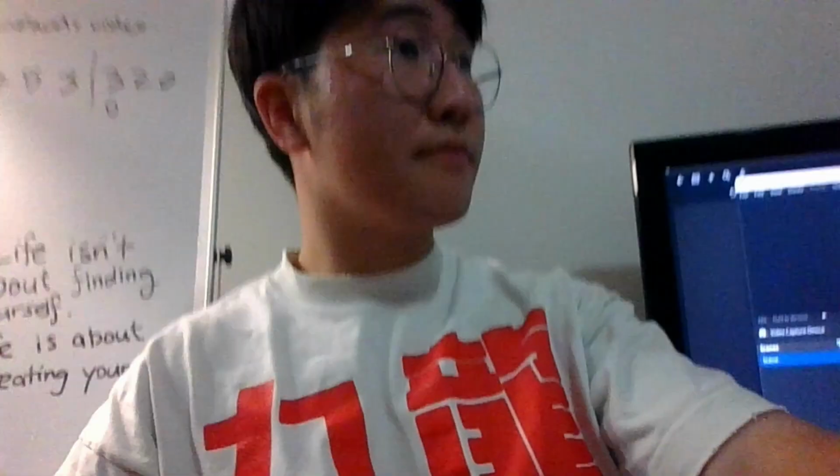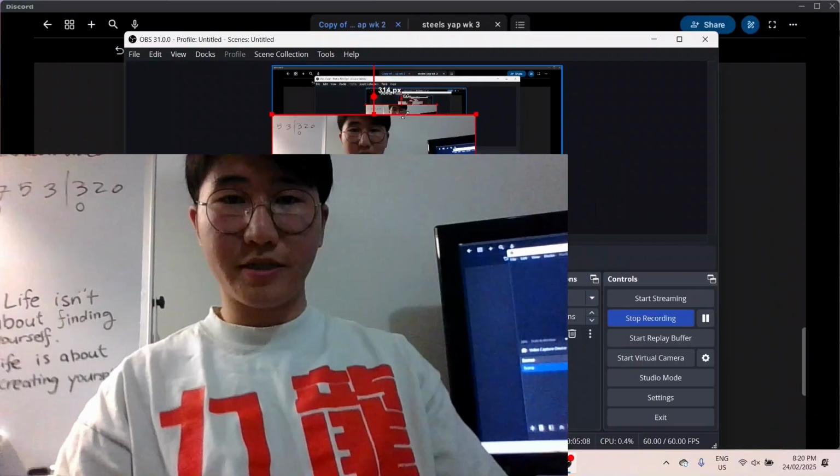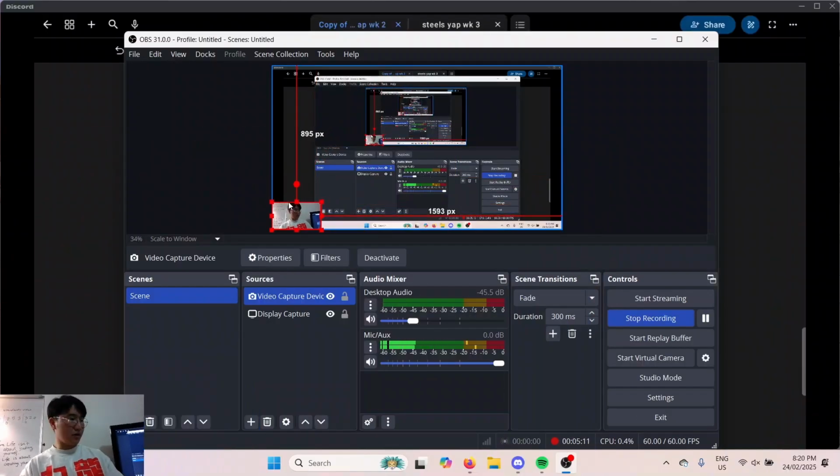I have a question. Which one's the major and minor axis? It depends on your shape. For this shape and for an I-beam, you're going to have a very distinct major axis. Did you do it by inertia? Yeah, exactly. That's exactly right. It's whichever inertia is stronger. Yeah, moment of inertia.